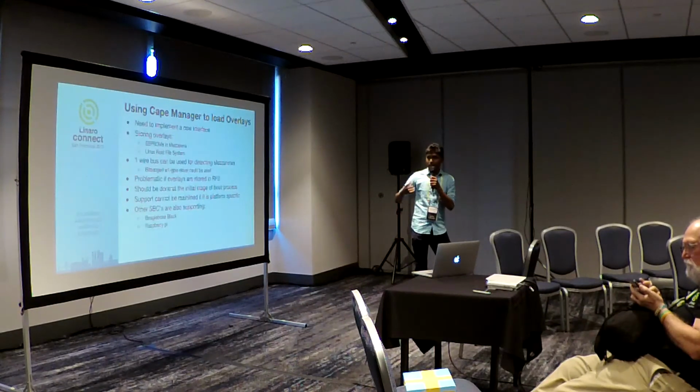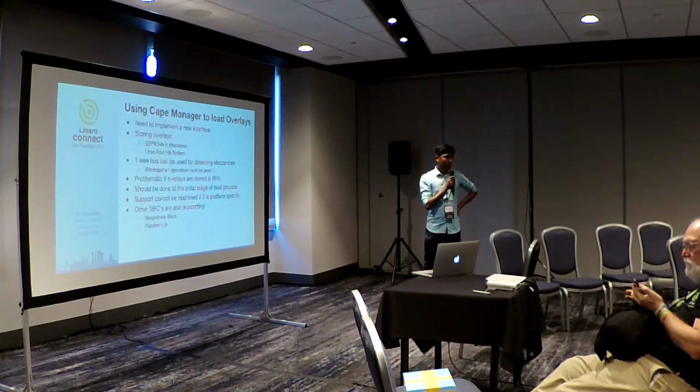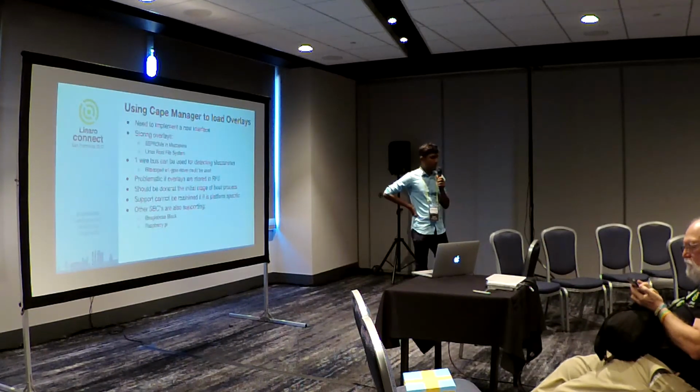It could be very problematic for detecting that. At the time of loading the overlay, we might have finished a lot of steps, so it will be very problematic for the GRO kind of things. So it should be considered, and it should be done at the initial stage of the boot process. If you are storing it in the root file system, I don't think it is possible. But if you are storing it elsewhere, it may.